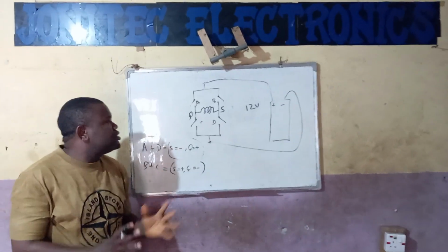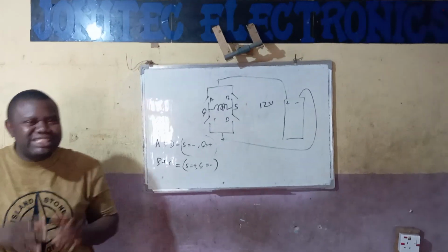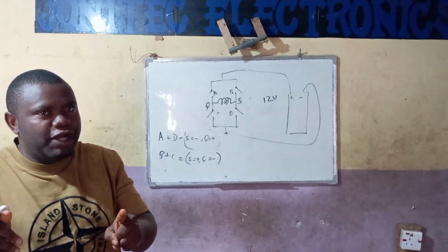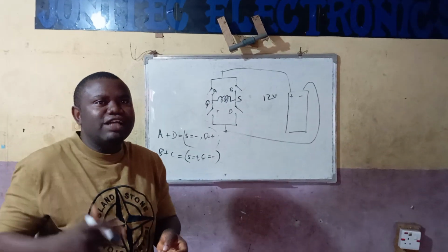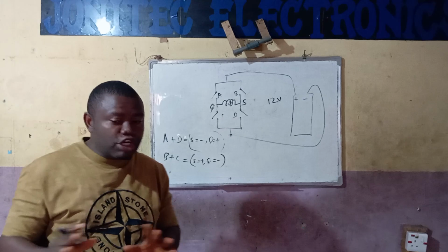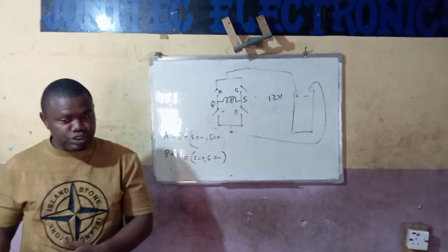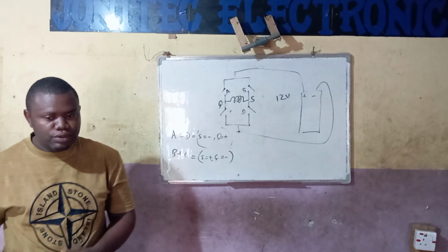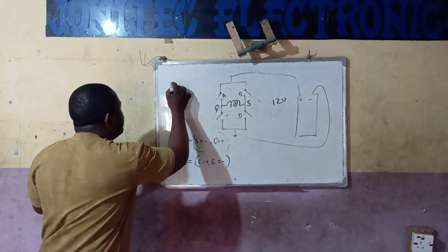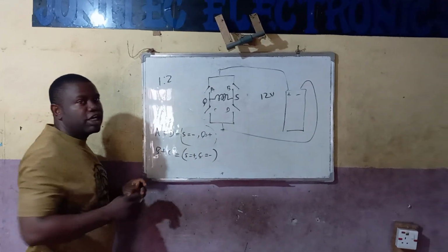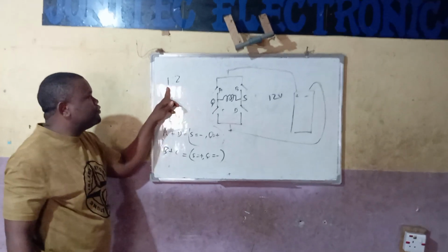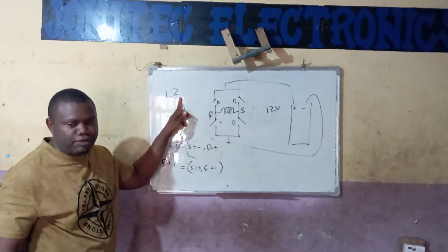And once that 12 volts AC enters into a step up transformer, the transformer takes in that 12 and steps it up. We talked about the transformer stepping up ratio the last time we came, right? If we have a 1:2 transformer, it means if you put 10 volts in this side, you get 20 here.